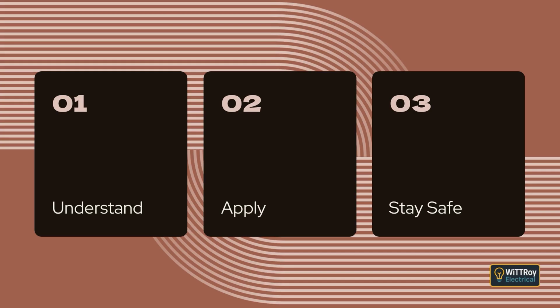Clause 2.2.4.2 Voltage. Equipment must have a voltage rating that matches the system voltage. Clause 2.2.4.3 Current. Equipment must carry the normal load current and withstand abnormal currents long enough for the protective device to operate. We think about inductive loads, heating loads, and any special characteristics.